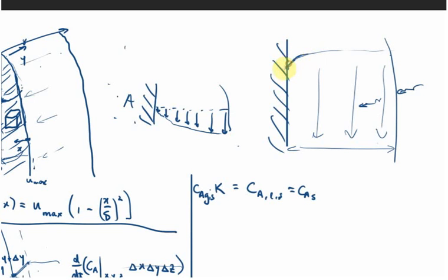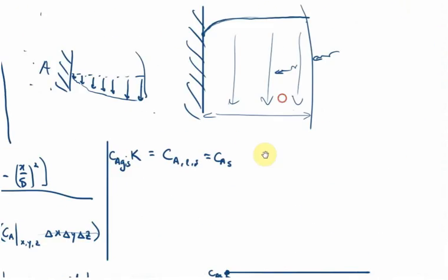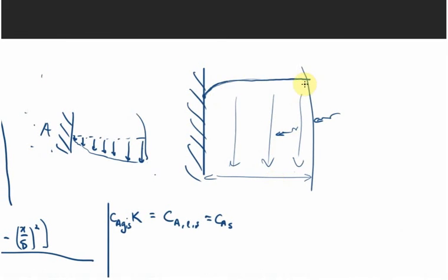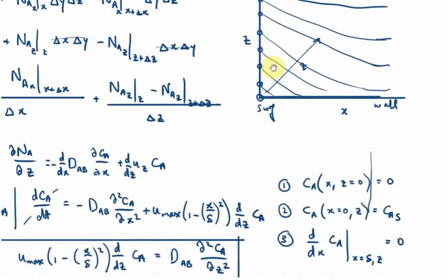So we are definitely going to get a zero velocity, but it might level out if we look far enough down the tube, that we can treat this entire velocity as in effect on average close to u max. So we can replace that whole velocity field by just the u max value, and so that's how we can translate the governing equation itself.